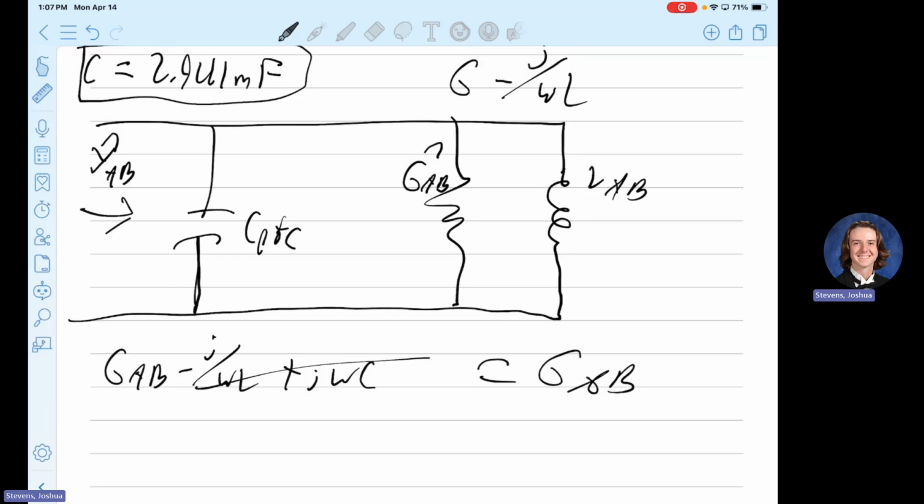Any questions? I see some confused looks, but it might take a sec. In terms of admittances, when they're in parallel, they add up like resistors in series. Y'all agree with me there, right? So if we were to have this capacitor in series, it would mess up that adding. We'd add these together like they're in series. But then if you were to have that capacitor here, it'd throw off the addition.